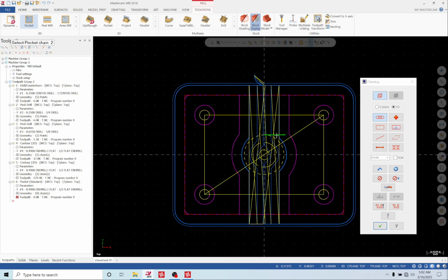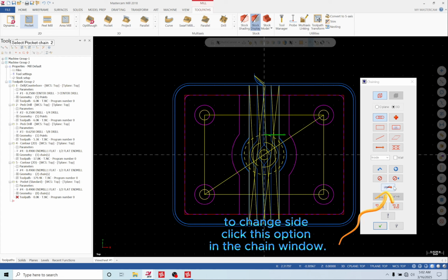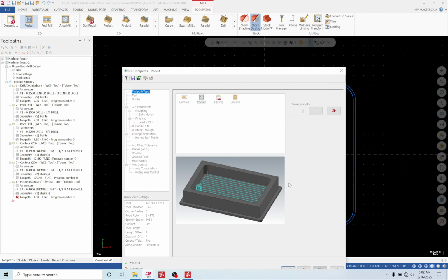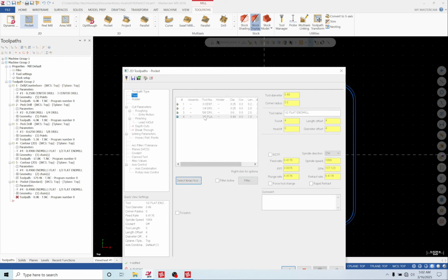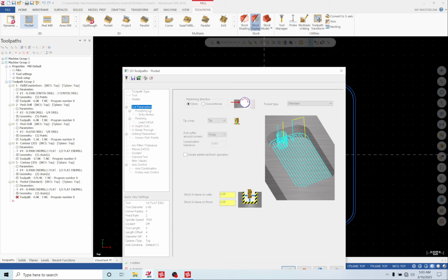As you can see, this is in the wrong direction, so we want to flip it because we're going to go on the left in the inside. So that's our chain. We go to our tool. Everything could be done with the same tool, so we're just going to keep working with this one. Rapid retract out to save us time. Feed. We can go a little fast once we're in there. Since we already have a clear path down the middle, we're gonna plunge in pretty fast.